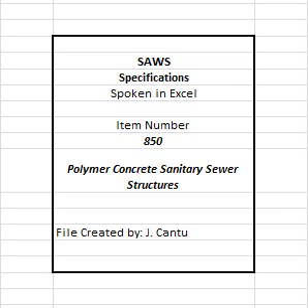All effort, materials, or other costs shall be solely at the contractor's expense. B. Vacuum testing. Structures shall be tested after construction/installation and backfilling with all connections, existing and/or proposed, in place. 1. Drop connections and gas sealing connections shall be installed prior to testing. 2. The lines entering the structure shall be temporarily plugged with the plugs braced to prevent them from being drawn into the structure. 3. The plugs shall be installed in the lines beyond drop connections, gas sealing connections, etc.